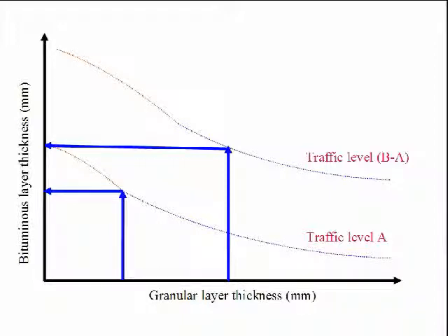Because the 100 millimeter overlay I put in this cycle will deteriorate and probably convert to some form of equivalent granular layer, or maybe better than that. So next time I put a 100 millimeter overlay, I'm actually providing lambda into 100 millimeter of overlay, because I'm getting some additional thickness as my benefit.